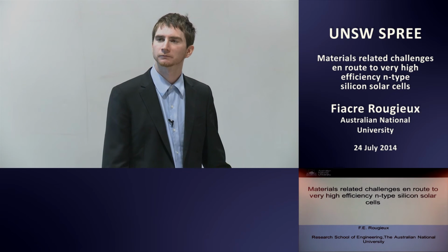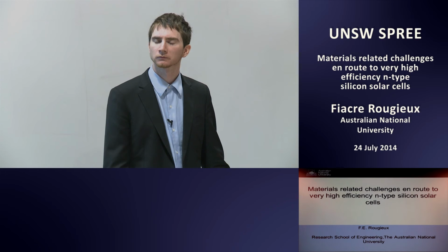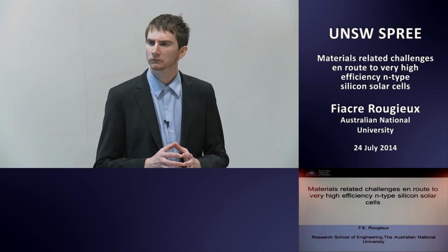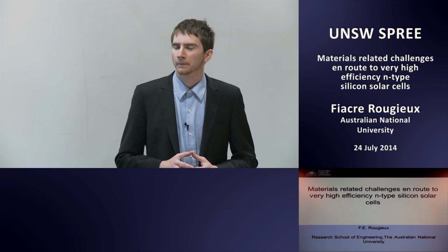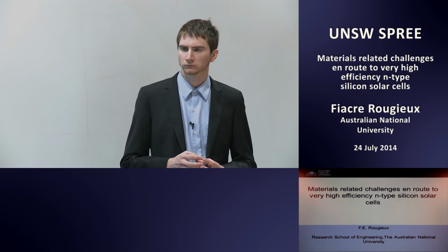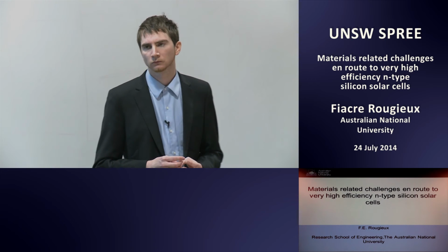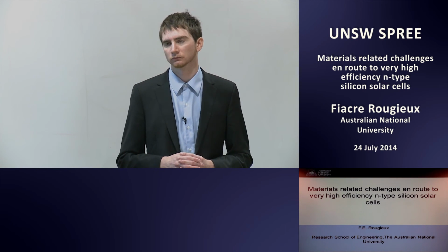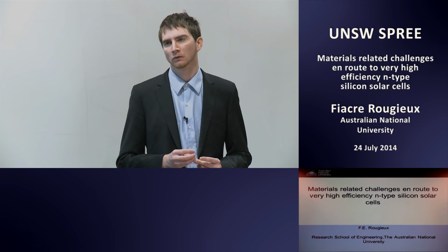Yes? Yeah, two questions. Your defect deactivation at 360 degrees is of course something that is specific to that type of defect, that vacancy oxygen complex that you mentioned. Do you think that is very representative for all CZ wafers? Of course, I would expect that if you have a different supplier growing at a different rate, or maybe even from the same supplier from a different part of the ingot, that a completely different type of defect would dominate, and then the deactivation temperature would also change. So do you have any comments on that?